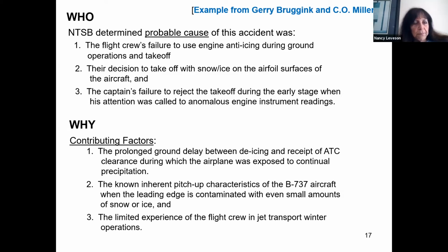So, for example, who? Well, the NTSB in this accident determined the probable cause was the flight crew's failure to use engine anti-icing during ground operations and takeoff, their decision to take off with snow and ice on the airfoil surfaces of the aircraft, and the captain's failure, you keep seeing this word failure, I'm going to come back to this, the captain's failure to reject takeoff during the early stage when his attention was called to the anomalous engine instrument reading.